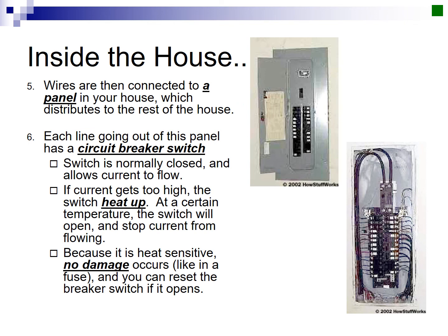All right, so then all the electricity goes into your house, and it's connected to a circuit breaker. If you don't know where your circuit breaker is, please go ask your parents or your guardians where it is. It's extremely important to know. Why? Because if you ever have an electrical fire or anything going haywire, you run down and flip the circuit breaker, which cuts off all electricity immediately to that location. If you don't know exactly which one, because there are a lot of different circuit breakers, know where the main circuit breaker is and flip that one so that it turns off all the electricity to your entire house, and then you can figure out where the problem area is a little bit later.